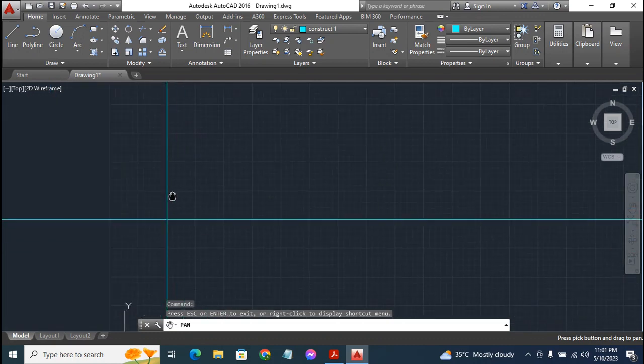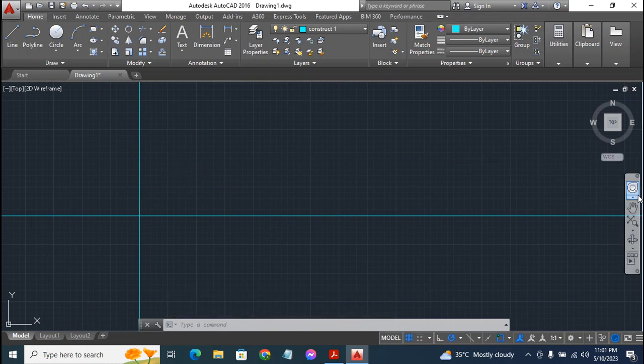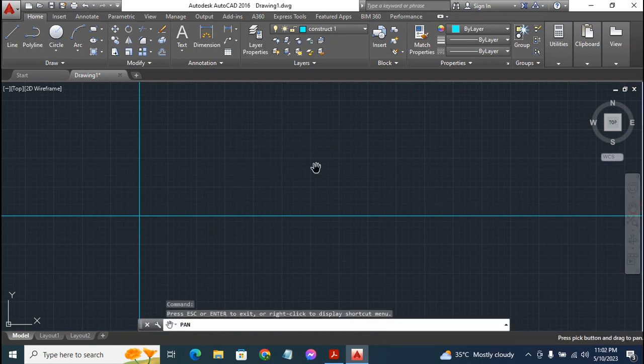So next up, we've gotten the entire length of our drawing to be 240. So I'm going to offset at a distance of 240. I'm going to pan the model space a little downwards, so that we'll have enough space for our drawing. Go to the right side on your screen where my cursor is right now.